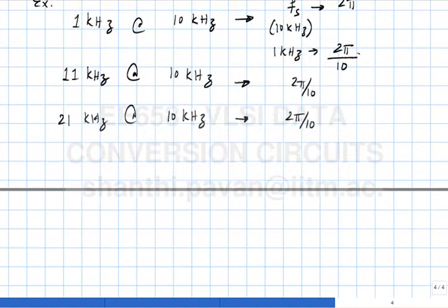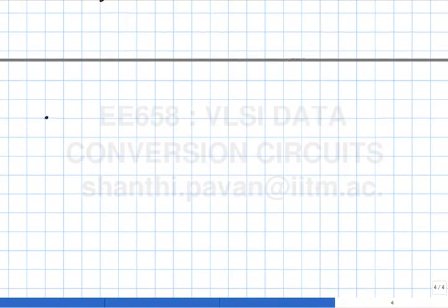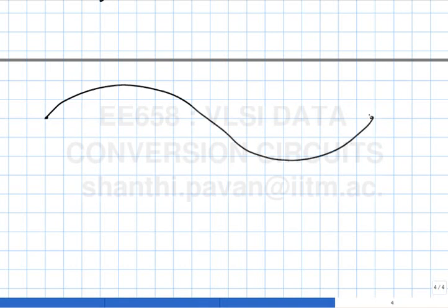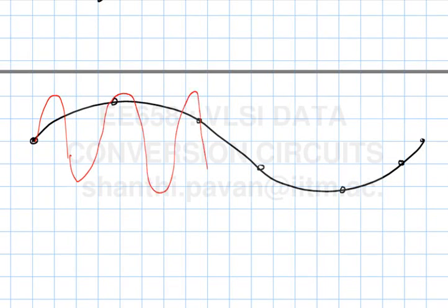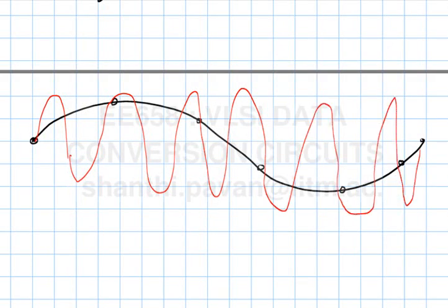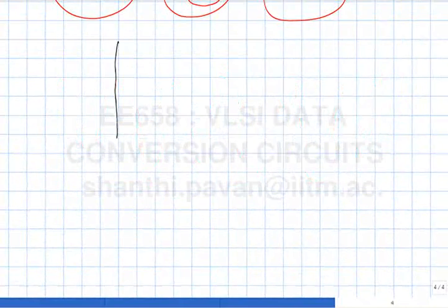Physically what's happening is that, let's say this was the original sine wave and it was being sampled at these points. When you say aliasing, it basically means that you can draw any number of sine waves which pass through all these points. That's all that aliasing is. Real signals have noise.